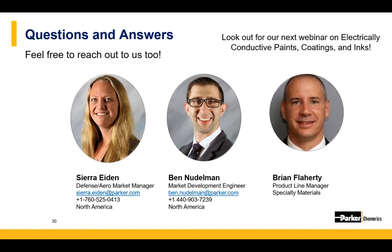Yeah, I think so. So those three: particle size, shape, and surface area. Chomerics does significant testing on our conductive fillers to understand exactly the size. Typically, we use Microtrac and do a particle size distribution because most of these particles, you don't get one particle size. It's usually a particle distribution for these different conductive fillers.